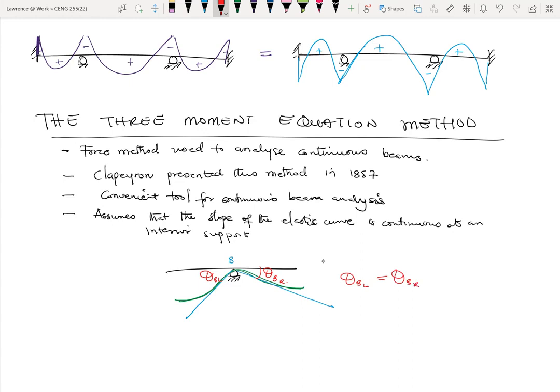But for simplification, if you do a proper three-dimensional analysis or experiment of a beam in terms of how they behave when loads are applied to them, there's a slight difference in the rotations at the point B, right? But for the purposes of simplification, we can assume that these differences are very minute and might not affect the overall behavior of the structure.